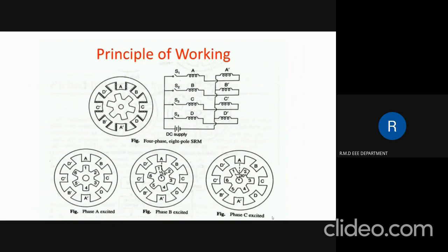As the speed increases, the load torque requirement also changes. When the average developed torque is more than the load torque, the rotor accelerates. When the torques balance, the rotor attains dynamic equilibrium and the motor attains a steady state. At steady state condition, the power drawn from the mains is equal to the time rate of change of stored energy in the magnetic circuit.